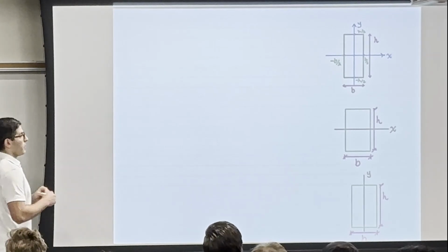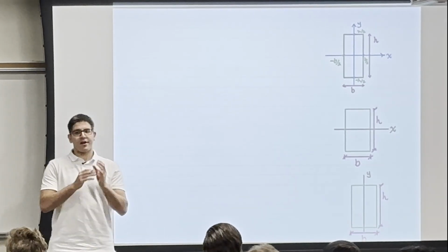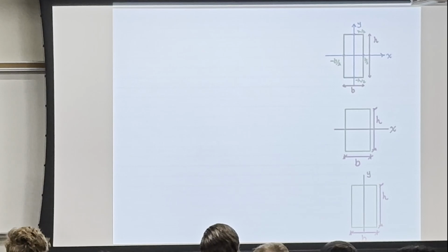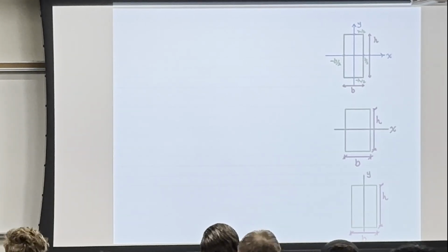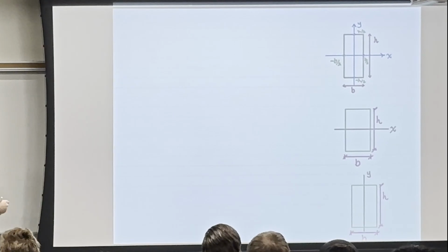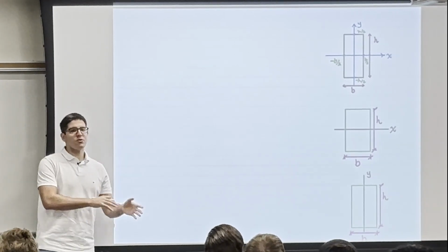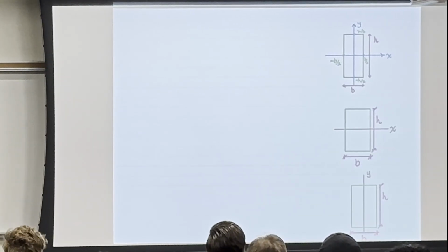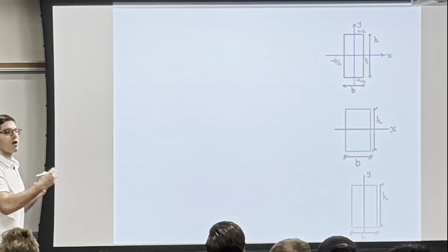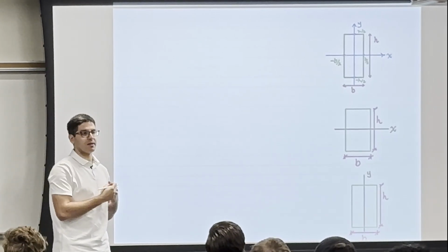And the first moment of area is area times distance, so it's inch to the power of 3, for example. And I've been asked, what is the physical meaning of inch to the power of 3? Is it a volume? No, it's not a volume. It's a new thing for you now, so just program yourself on that. The inch cubed here doesn't mean volume. It means the distribution of the area, or how far that area is from the axis of bending, or the centroidal axis.